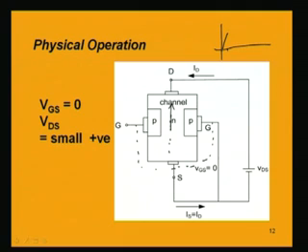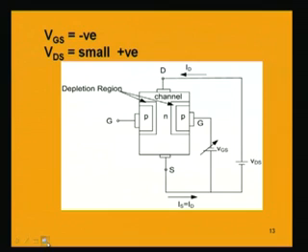So, initially if VDS is small, when we increase it a little, the current increases. Then if we go on increasing the VDS, another phenomenon will occur, which is saturation or pinching off, that we will be discussing. But next let us now apply a negative potential between gate and source.